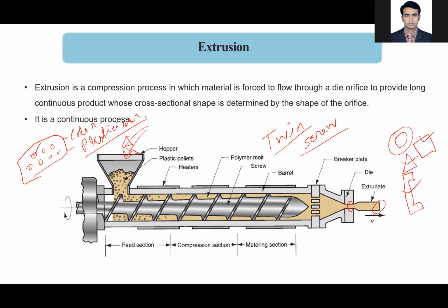If you want the final product to be flexible, like you want to bend it very easily, then you use the plasticizer. Otherwise, if you want to produce rigid plastic, that is very strong plastic, then you have to reduce the amount of plasticizer in the material. Sometimes these plasticizers are included in the resin grains, sometimes not, and you have to add it manually.